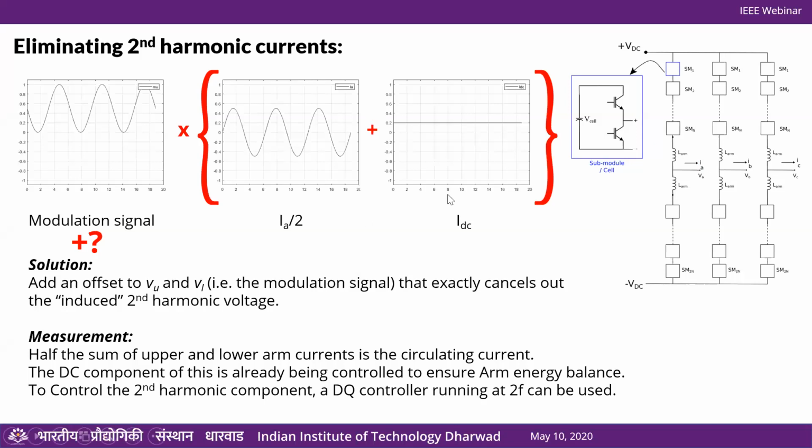The next question was how capacitors are sized. Theoretically, capacitors are sized by just looking at ripple. So you design your topology, figure out how much acceptable ripple you have based on your output load current, IA, IB, IC.